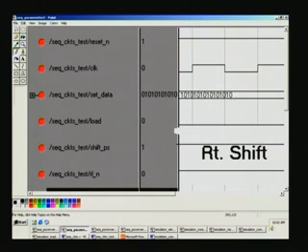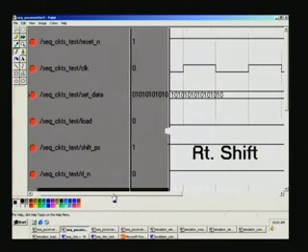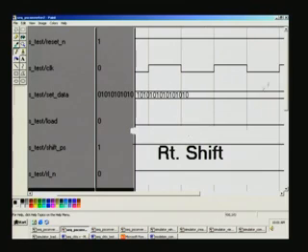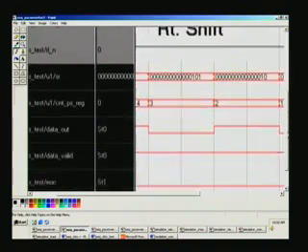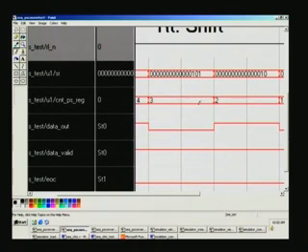So set data is this, and this right shift is still high and shift has been asserted high. This counter has come down to 4 here, 3, 2, 1 and so on. You can still see that some of the patterns are still here, 1 0 1 here, and once you right shift, this one gets dropped.